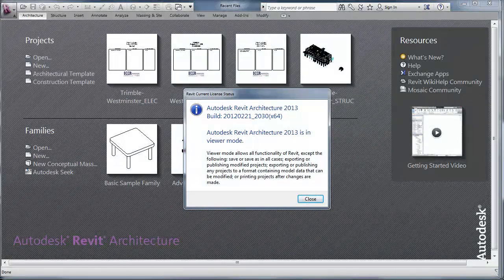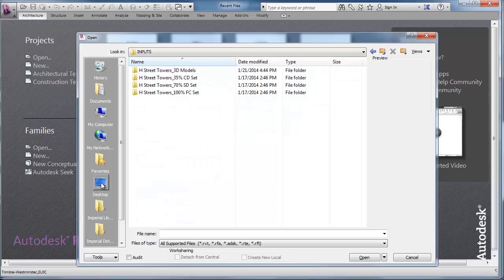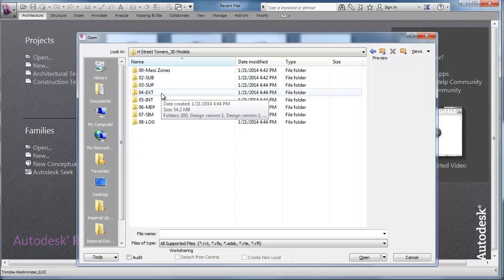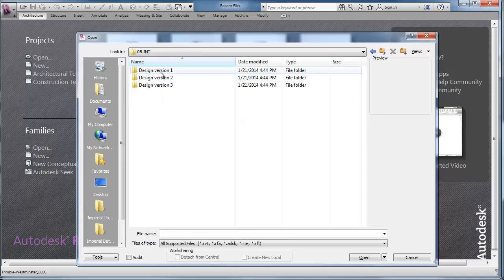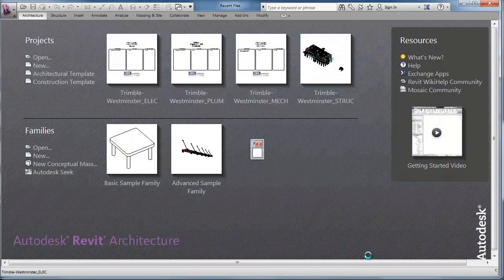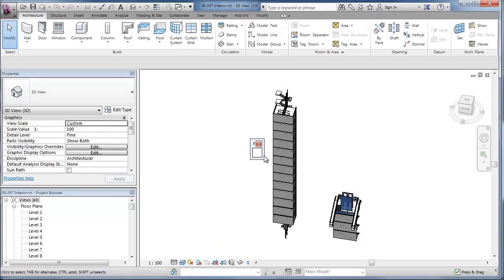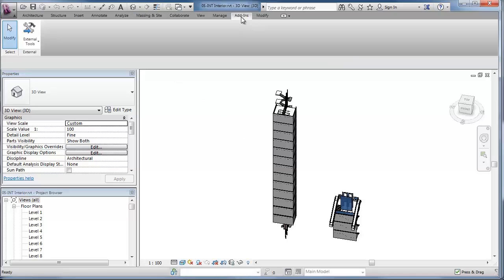After that, we want to publish the interiors content. That was created in Revit, and notice here that I can use Revit in demo mode and that I don't need a full license to send the model into my project. I'll navigate here to my interiors model and find the first version that we received from the design team. Open up the project and then navigate to the 3D screen. All of the content is sent from the 3D view into the project.